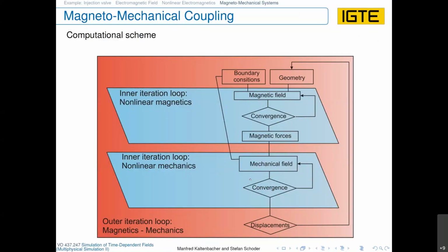Then we will not be able to solve this with this smoothing mesh technique. You can use this for some time, and then it will be necessary to remesh your computational domain, which also means you have to interpolate your results from the old mesh to the new mesh, which is also very challenging.